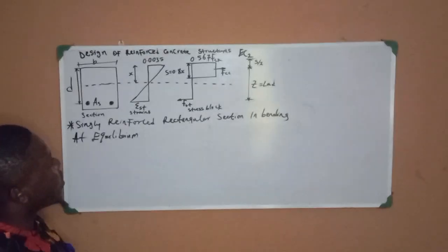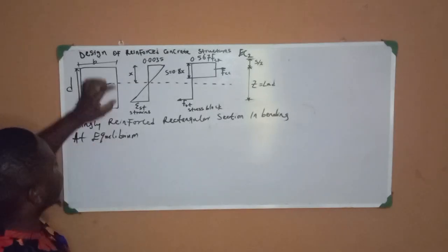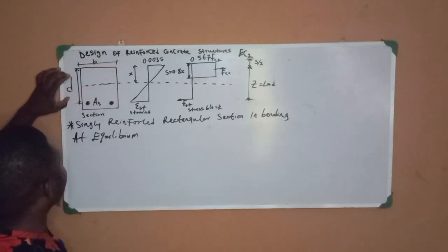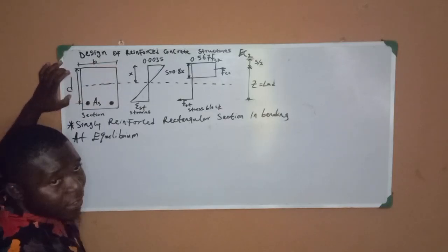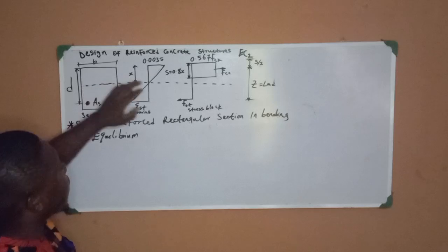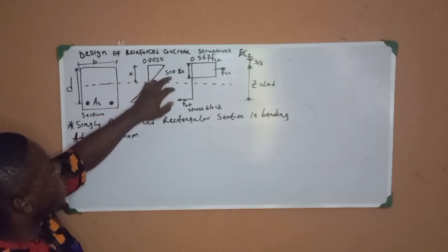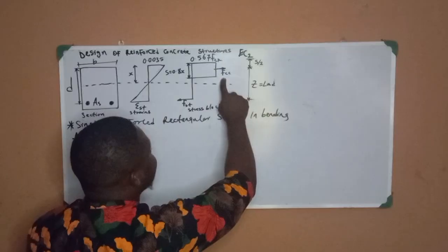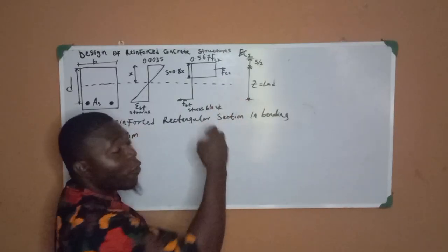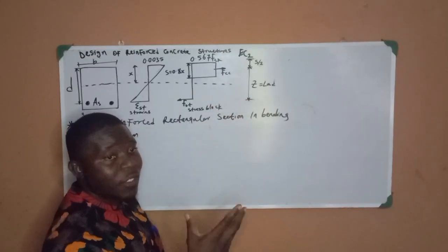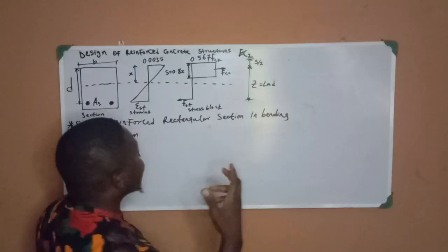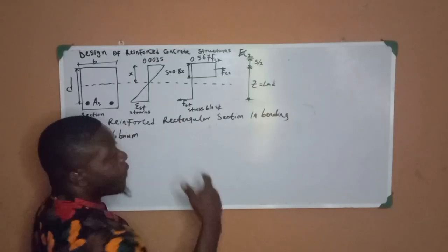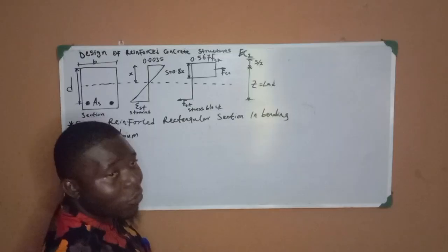You can see the X denoting the neutral axis, and the d denoting the effective depth. You can see your s, which is equal to 0.8x. Fcc denotes the force in the concrete in the compression zone. Now, your Fsd is the force in the tension zone.